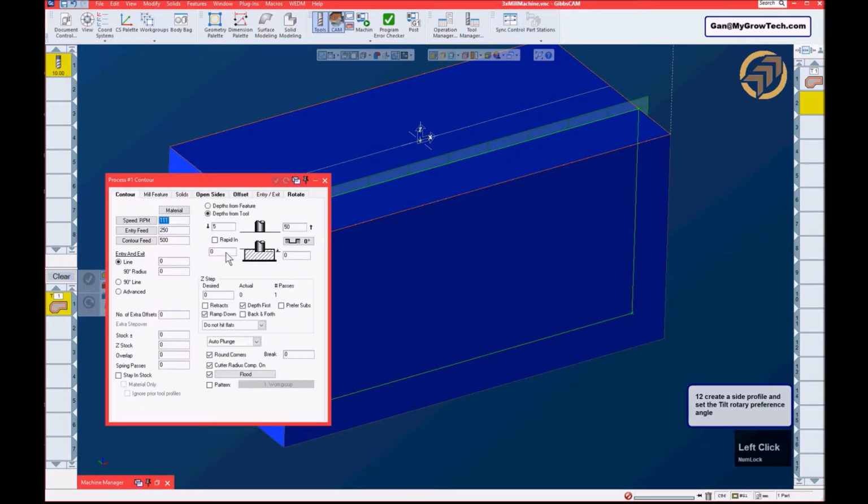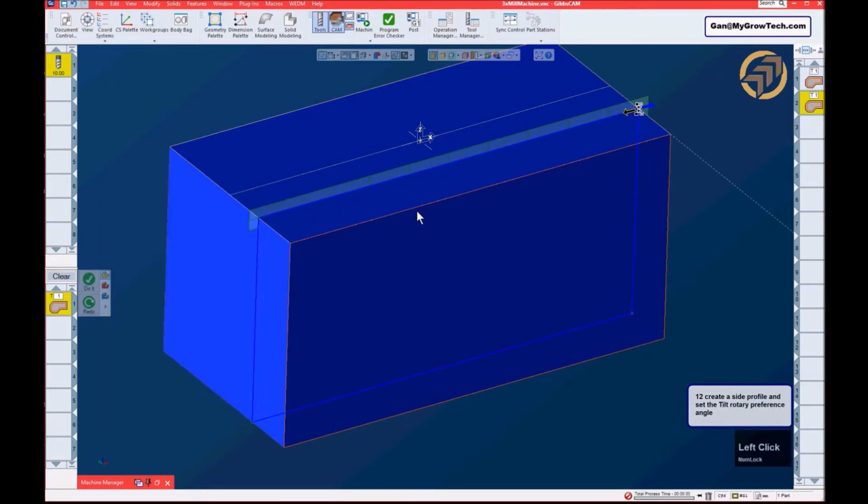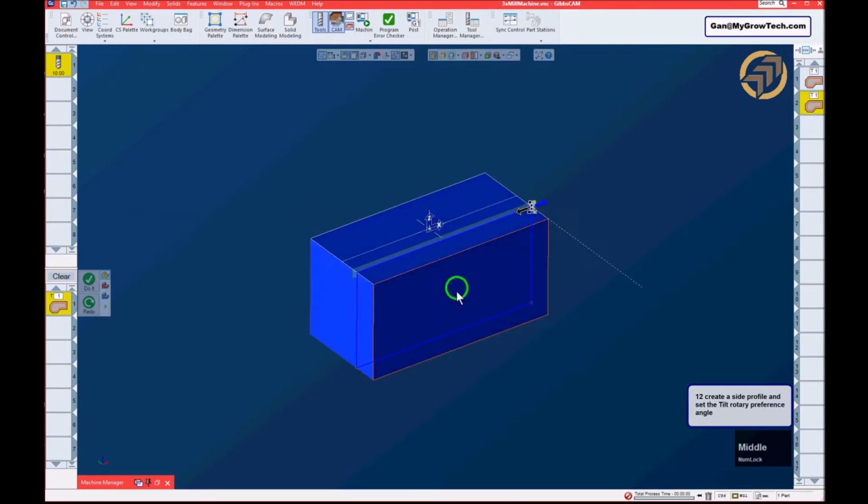And let's capture the height. Use the alternate key. Capture this height. Also here, this height, 25. Let's put 30. It's good enough. Give it 100. The rest is okay. Let's choose this control and do it. So now I have a profile in front.